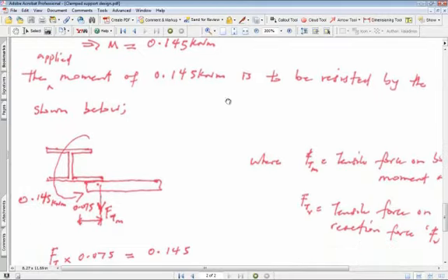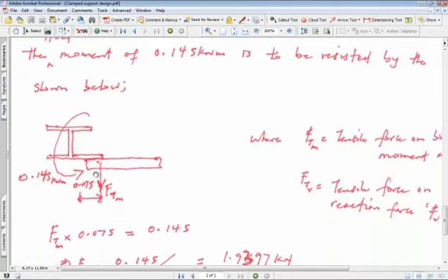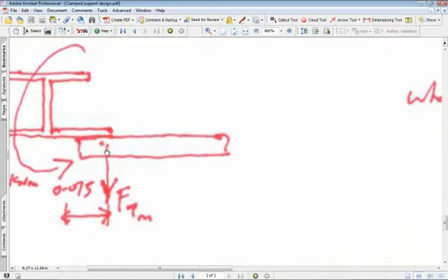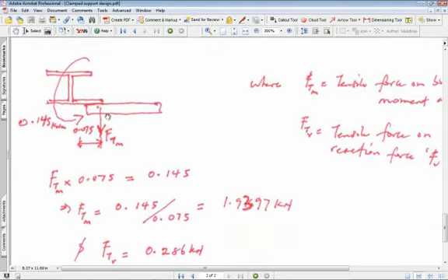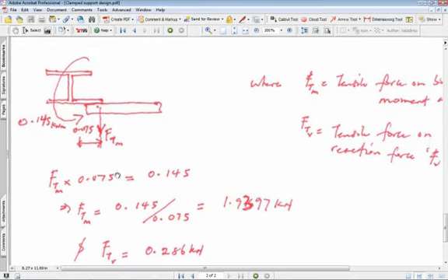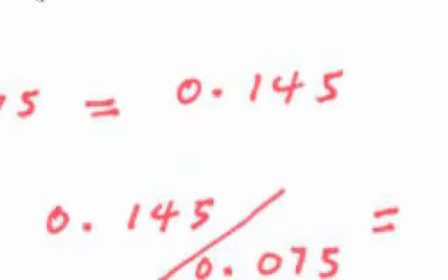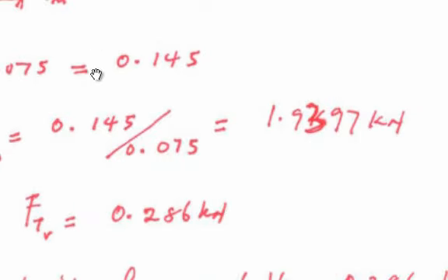After obtaining the moment and vertical force, the next thing is to determine the free body diagram of the action of forces on the bolts. When we sum moments about the eccentricity of the bolt to the end of the cantilever, we obtain the tensile force the bolt is subjected to.